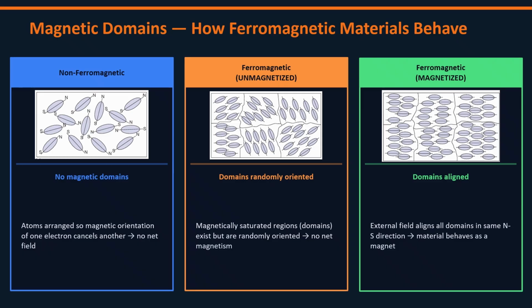There is a progression from weak magnetization through increasing alignment toward saturation. It also explains why excessive current is not automatically better. Once the useful magnetic response is established, adding substantially more magnetizing force may produce little additional benefit while increasing heating or other practical problems. The domain concept also helps explain residual magnetism.